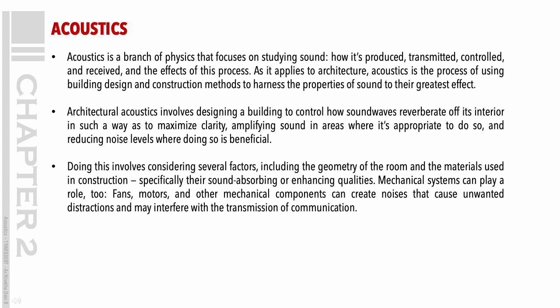Architectural acoustics involves designing a building to control how sound waves reverberate off its interior in such a way as to maximize clarity, amplifying sound in areas where it's appropriate to do so, and reducing noise levels where doing so is beneficial. Doing this involves considering several factors, including the geometry of the room and the materials used in construction, specifically their sound-absorbing or enhancing qualities. Mechanical systems can play a role, too.